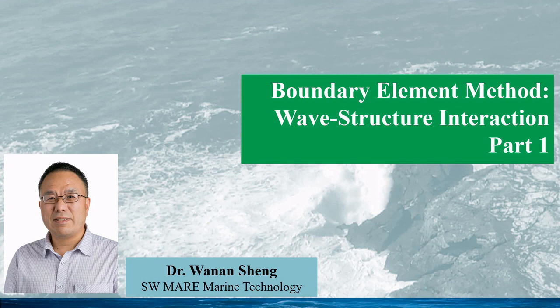In this talk, I will first show the difference between the body flying in the air and the structures on the seas in terms of constructing the boundary element method, and then how we can use the Green's theorem and the de-singularisation method to establish the boundary integral equation for the wave structure interaction, and why the special Green function is chosen for simplifying the boundary integral equation, so that we can implement the numerical scheme for the wave structure interaction.